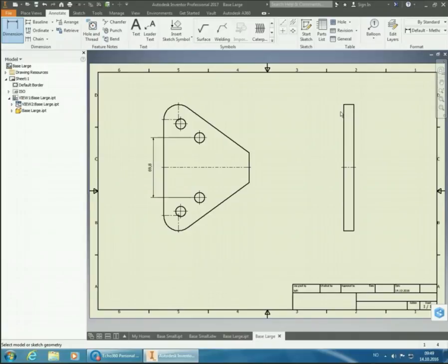But of course, if the centers of the bolt holes where you're going to bolt it to has 69.8 between them, then the holes that your bolts are going through also need to have that. So in some cases you simply have to endure the fact that you're going to put in dimensions where you have point something millimeters.